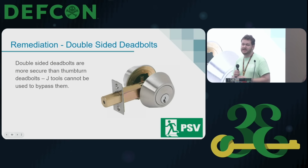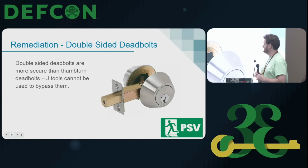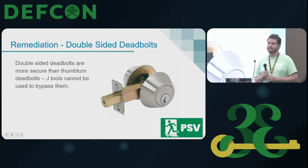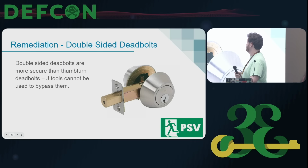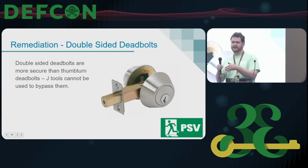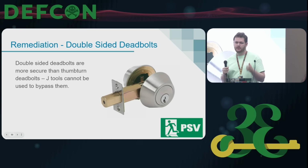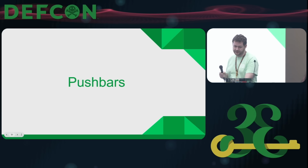So again, the best remediation for this is going to be eliminating the deadbolt lock itself, the thumb turn mechanism on the inside. You can use double-sided deadbolts that would completely remove the opportunity for a J tool to be inserted and turn anything because there's not going to be anything in there for them to turn and to deactuate. J tools cannot be used to bypass these systems, obviously, and it's a whole lot more secure than just having the tool be able to be used because of a gap. So again, that's where proper installation comes back in. And then having the thumb turn mechanism be gone itself is also going to be important.